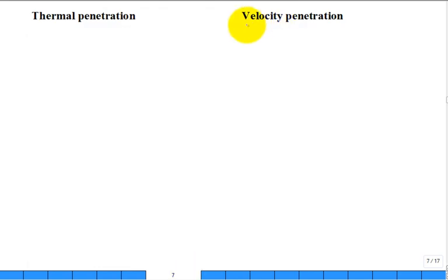In fluid mechanics, you talked about the velocity profile. In heat transfer, especially when we get to convection, we're going to talk more about the thermal temperature profile. If I turn the problem around and plot it a little differently, as a function of y instead of x, distance out into some semi-infinite medium, where y starts at 0, that's our boundary.